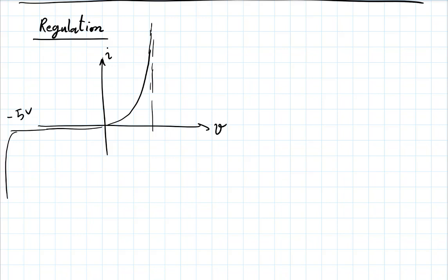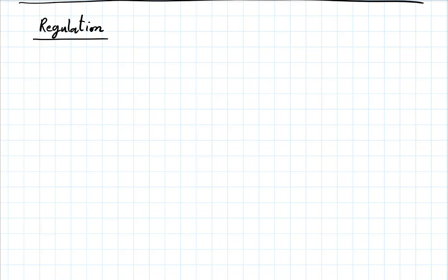And these are Zener diodes, diodes that have been made particularly so as to have a very sharp and straight vertical descent at some well-defined negative voltage, and to operate in that breakdown mode. And so that's what we are going to look at. That's not to say you can't do regulation with regular diodes, but Zener diodes have been made to particularly have good characteristics there.